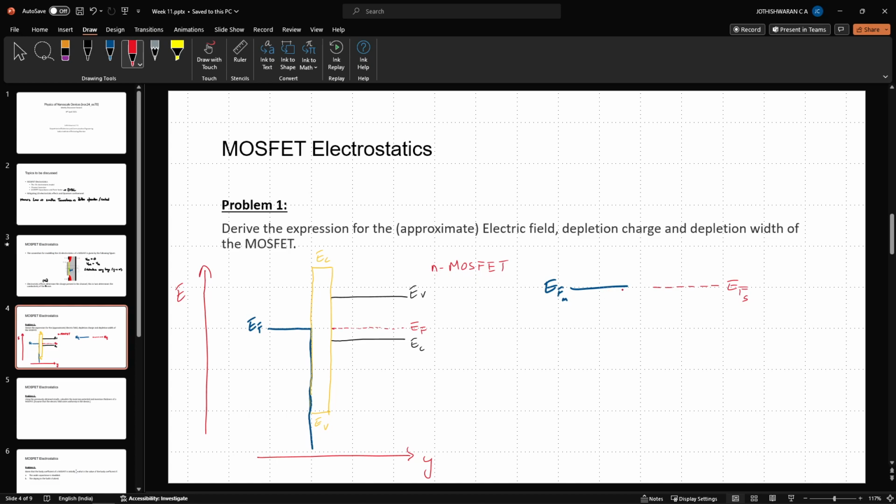No, I'm sorry. No matter what happens, since this is electron rich, this Fermi level will more or less not move. The more potential I apply, the more electrons it is going to pump through the oxide layer into my semiconductor. The semiconductor is initially p-type, and it is a hole rich region.